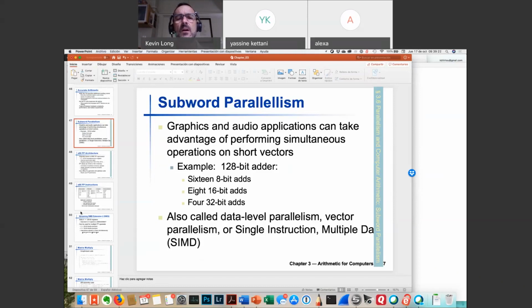One of the tricks that we can use when we architect these systems is to allow that string of calculations to happen on each of those pixels in as parallel a fashion as possible. So there are architectures that will allow you to handle a whole range of strings of data. Maybe you line them up in a special set of 32 registers and you put a math command in and you tell the system, run this math command on all 32 of those registers and put the intermediate result back in those registers again. And then I'm going to give you a different command and I want you to do that to all of the 32 numbers.